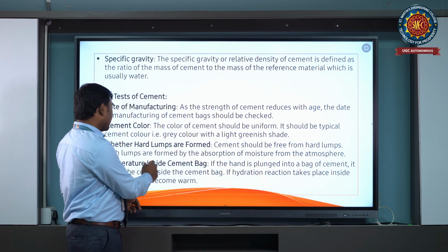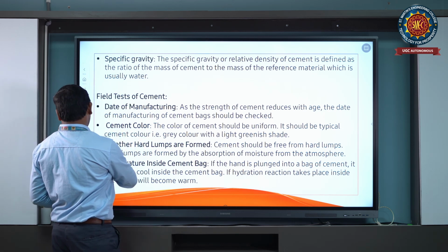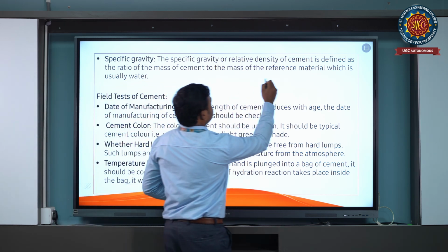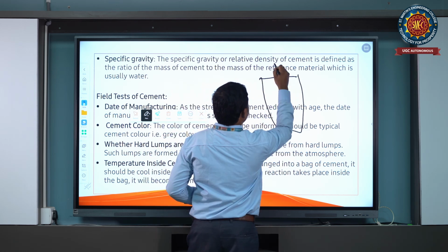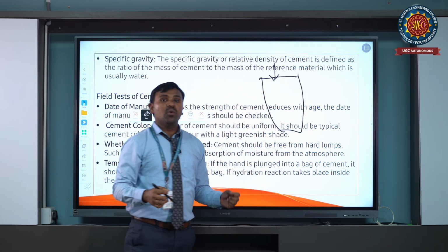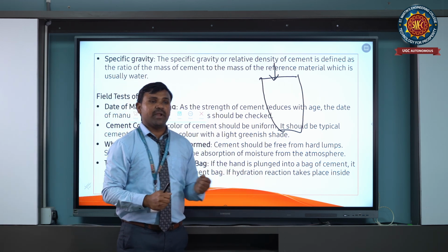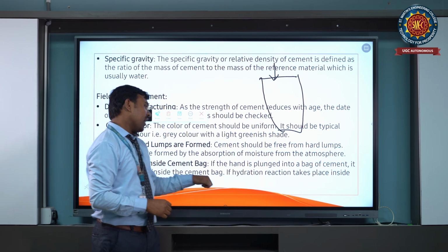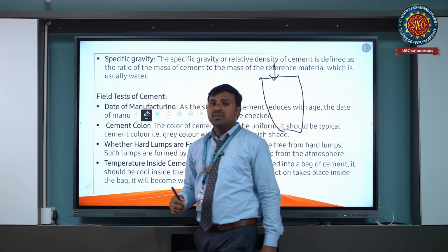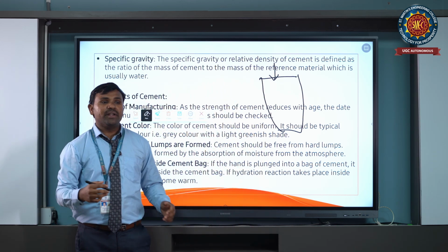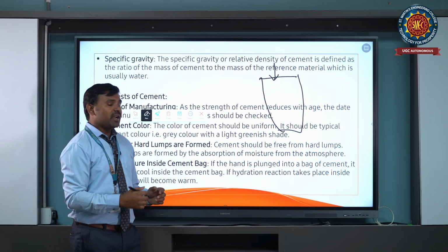And next, temperature inside the cement bag. While putting your hand in the cement bag, you should feel a cool temperature to know it is good cement. If you feel high heat in the cement bag, you should suspect adulteration of the cement, which is hardening of the cement.